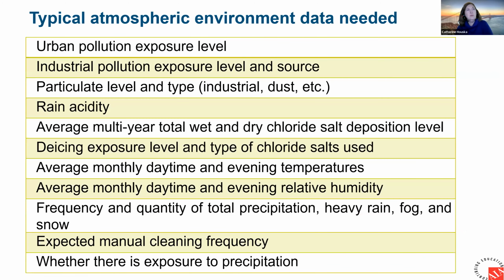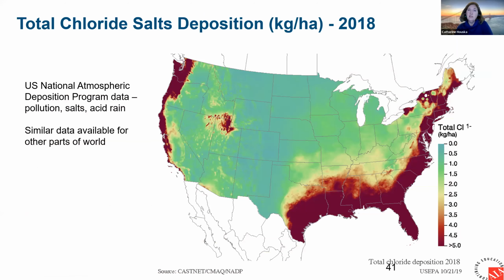And these are some of the pieces of data that you need to collect to better understand that service environment, such as pollution exposure, salts, acid rain, the time of wetness, in that, how much rain there is, how frequently are these thunderstorms, will anybody be cleaning it?